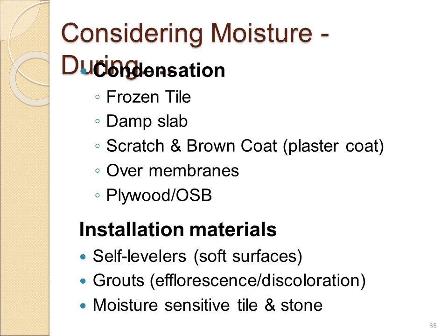As mentioned in a previous slide, we talked about plywood and OSB. They definitely can be affected by moisture and condensation. All of these things can be a factor, and they cause a bond breaker for mortars. One of the little-known factors with self-leveling products, for example, is that if you read manufacturer's instructions, they tell you that there should not be a wind that goes over the surface of the leveler. If a strong wind or a strong air force is over the surface of the leveler, it'll dry out the surface, and you can get a very soft surface on your leveler.